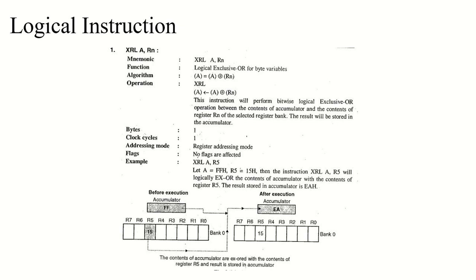Register addressing mode, direct addressing mode, register indirect addressing mode, and immediate addressing mode. So the same four modes which were supported in the AND operation and OR operation will be supported by the XOR operation as well. When the instruction is used to modify an output port, the value used as the original port data will be read from the output data latch and not the input pins. The same will happen in the ORL instruction and the XRL instruction as well.